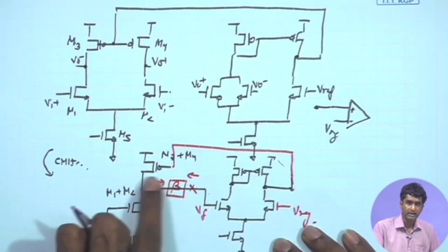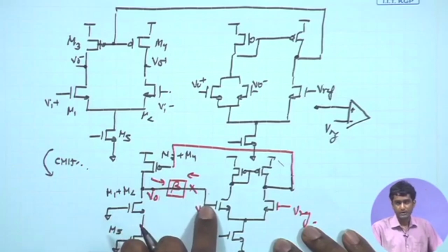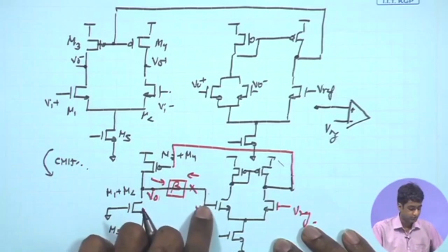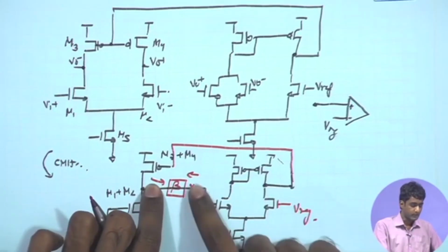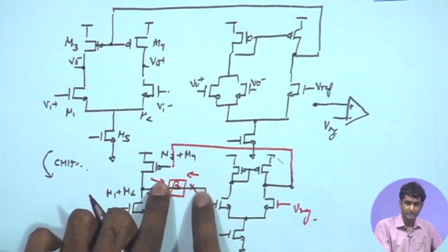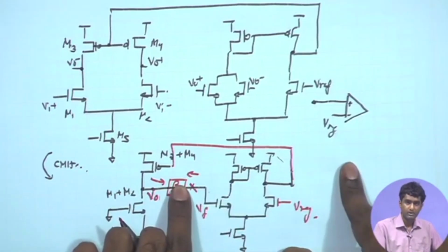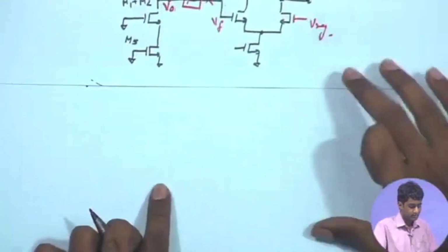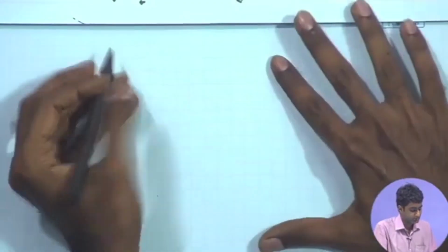So, if I am looking at the input port of the feedback network, once again at the output port we have series connection, and for series connection we know that we need to open circuit that point, and therefore, once again looking from the input port of the feedback network, we will just open circuit this point, and as a result you will have an open terminal coming at the final port. So, as a result we can draw the equivalent open circuit for this feedback amplifier.